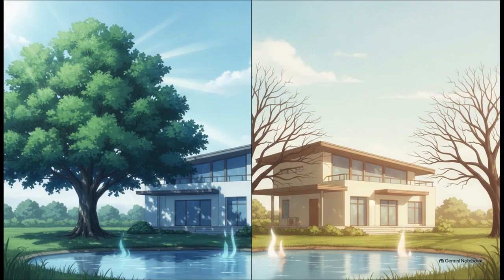Placing water bodies near buildings acts like a giant thermal regulator, smoothing out those drastic temperature spikes. And finally, if you're designing for a cold climate, your orientation should be slightly east of south. Why? Because it grabs the absolute maximum amount of solar heat due to the longer duration of exposure.